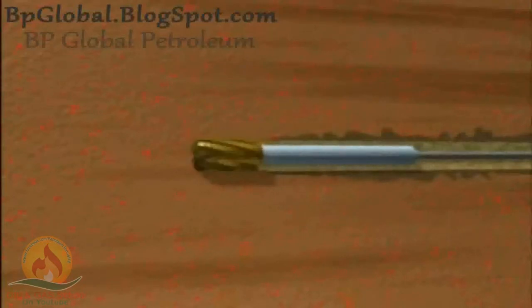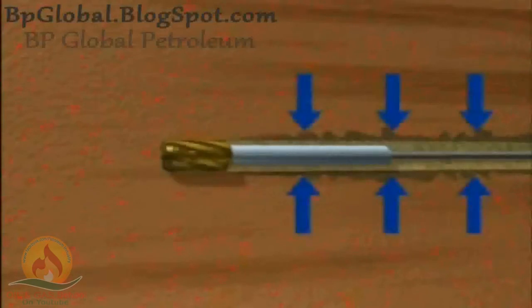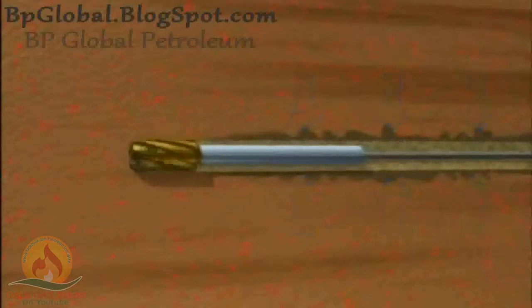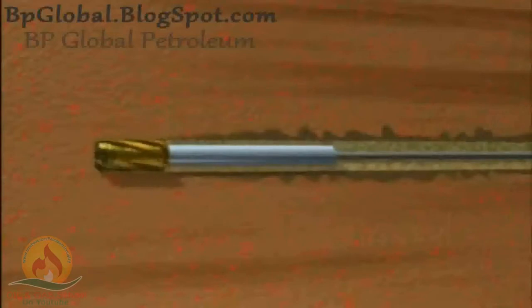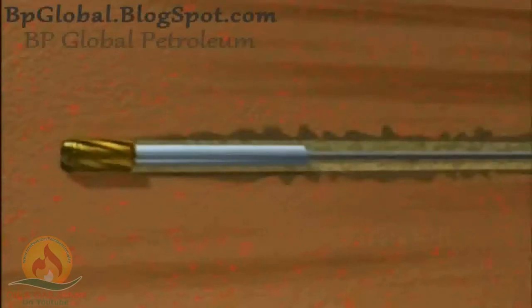Since the pressure in the hole is higher than the pressure in the rock, fluid and fines are lost to the formation. These losses cause damage to the near wellbore area, resulting in reduced production. Experience shows that even a short exposure to overbalanced conditions can severely impair the productivity of a well.